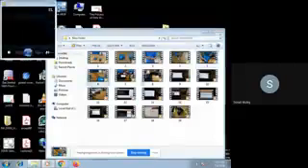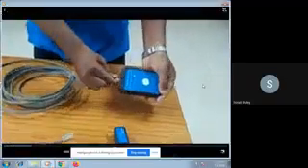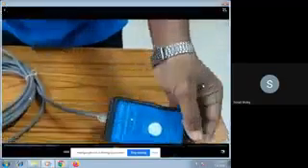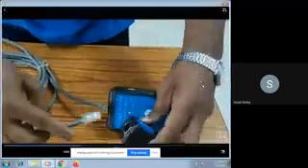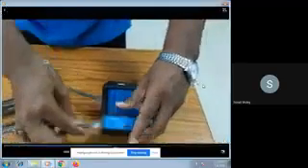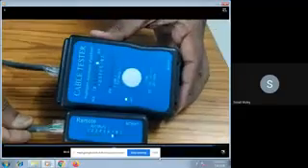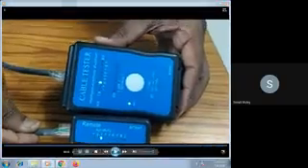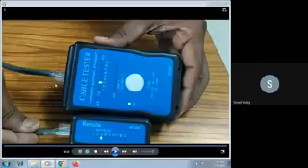After that we have to test whether the cable we have prepared is correct or not. Because if one of the wires is not properly placed in the connector, then it will not blink all the wires available on that cable tester. Here you can see each and every wire that we have connected in the RJ45 connector.